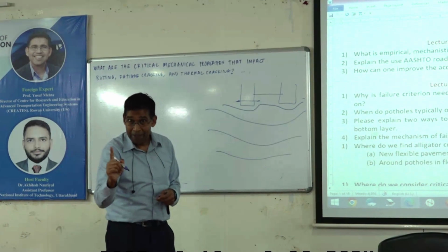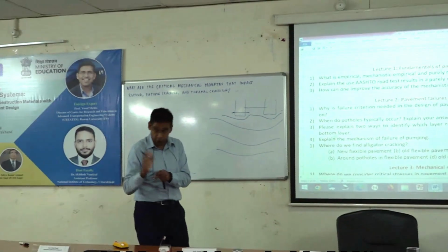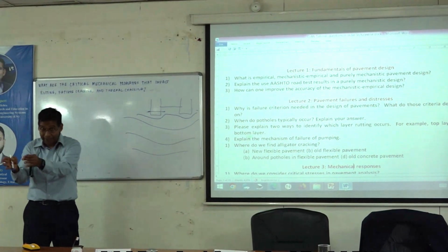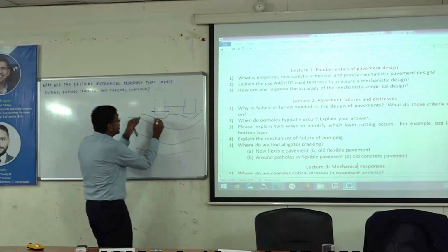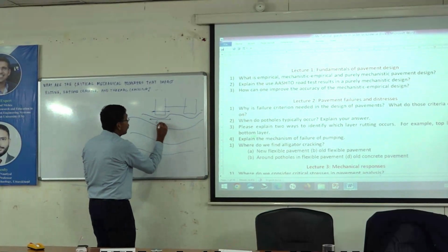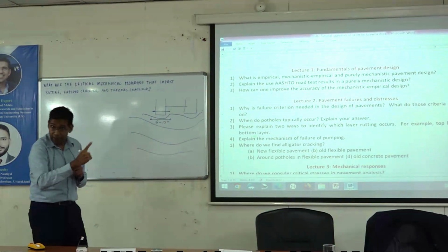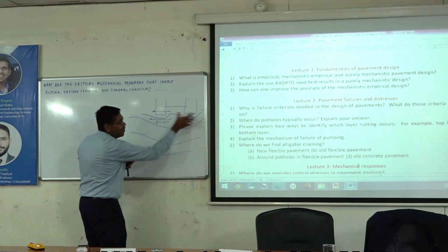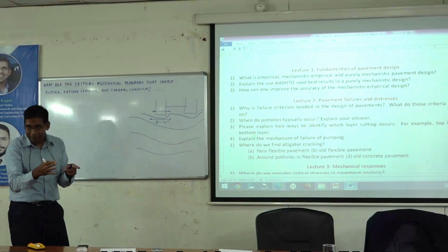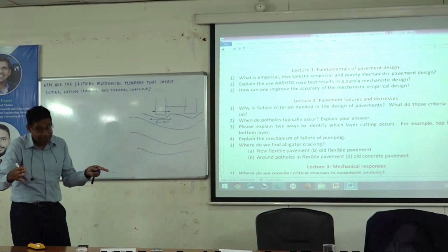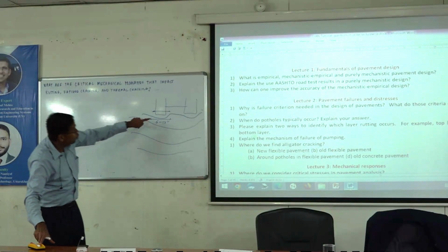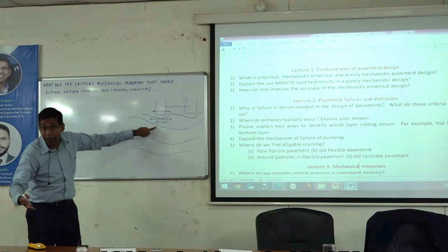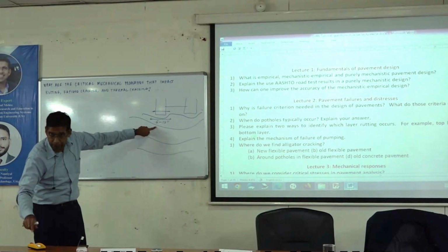They are wandering, so it's not going to change even once you have automated vehicles. Your vehicle itself has almost 6 to 12 inches of wander when traveling on the road. So you are not going to see a very tight rut depth along the wheel path. You are going to see a little widening either way. I made the difference between this and this seem very obvious, but it may not be that obvious. It's a much harder problem than that.